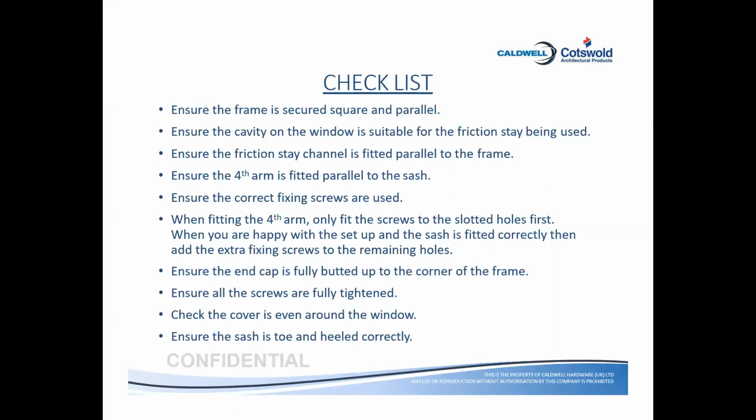In that way, the slider gets damaged and there is a jerk in opening eventually after final handover. And people blame that your arm is not good. But we suggest that you make sure the window is covered fully if there is civil work going on beyond fixing of this window.